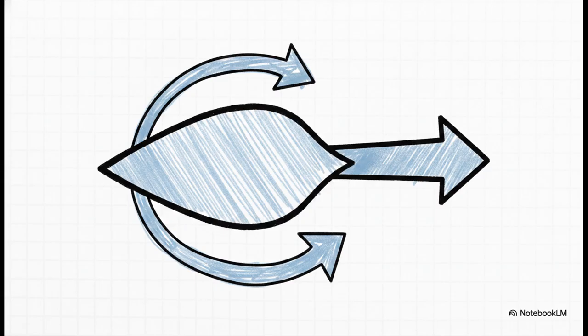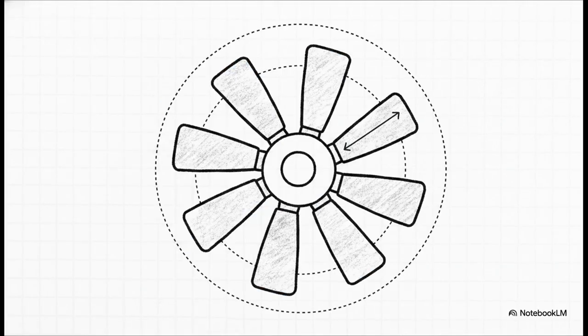It's brilliant. Now, to survive this violent, non-stop push and pull, the geometry has to be absolutely precise. The turbine relies on 8 perpendicular blades, and each one is crafted with a strict 125mm chord length and a maximum thickness of exactly 15% of that length. Nestled perfectly between a base radius of 200mm and an external radius of 300mm, it's a remarkably sturdy configuration built specifically to handle those extreme ocean forces without tearing itself apart.